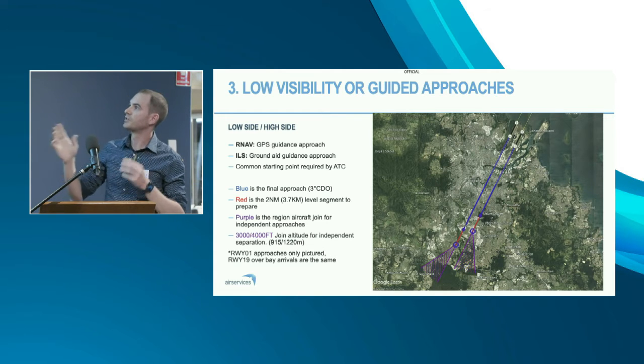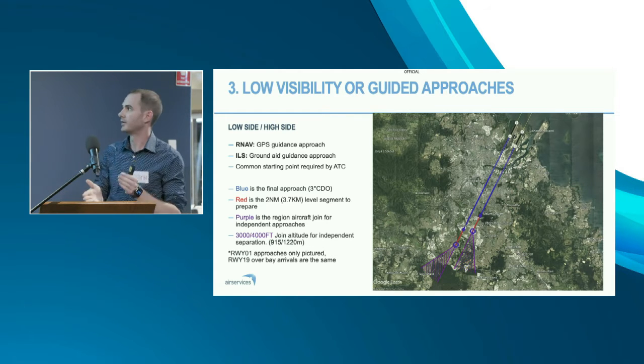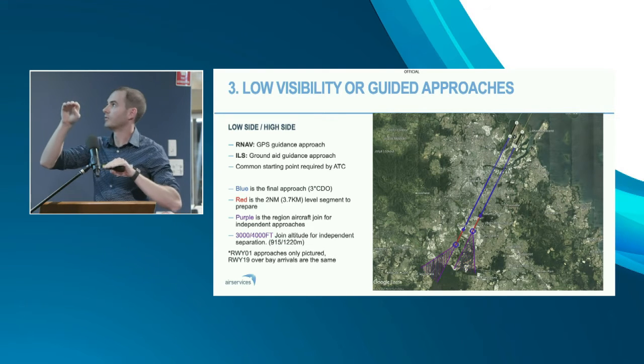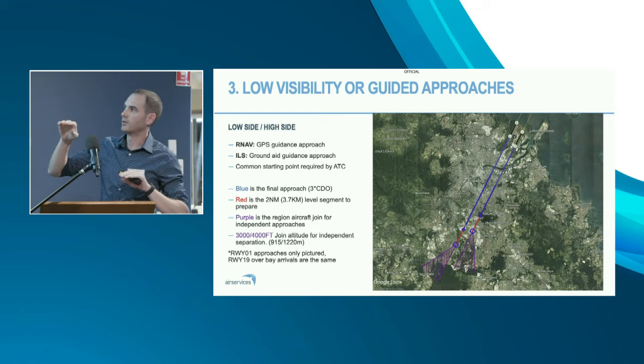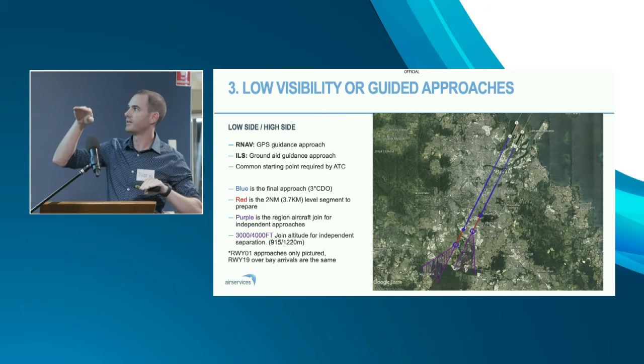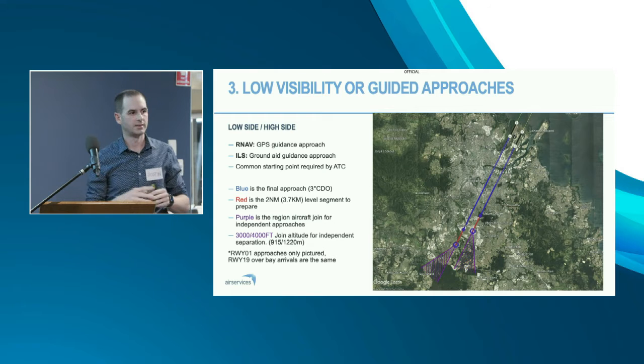And because there's two runways, now they actually have to consider one another. So what we end up with is a vertical requirement, a difference at the start of the arrival. So we have a high side and a low side, and they're 4,000 feet and 3,000 feet. That's 1,000 feet different, or 300 metres different. That's the international standard that makes it safe to arrive.